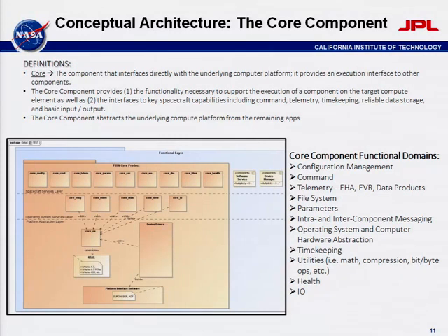Internal to the functional layer, this is kind of a blow-up of the functional layer, you see there's this flight software core, and then perhaps in a flight software system you would have other software services and device managers. The functional layer itself is layered. At the bottommost layer of the functional layer is the platform abstraction layer.